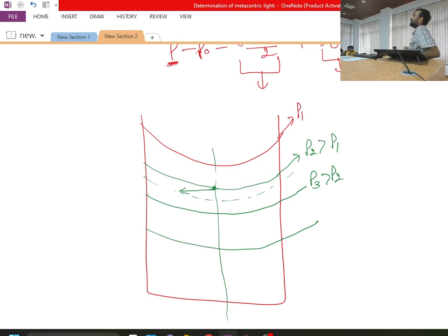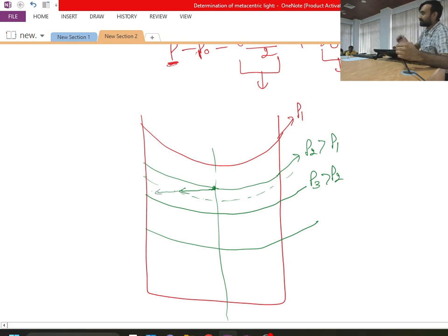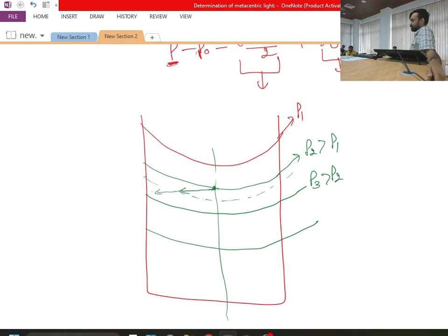But in this situation, with elevation the hydrostatic component is same, but we have some component because of the rotation of the fluid element. So even if I move in the radial direction at the same elevation, my value of pressure is changing. This is one important observation.